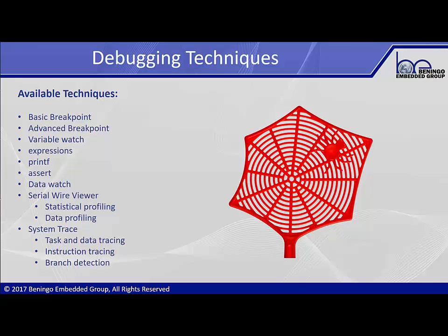So if you have a function that's blinking an LED, you may find that, for 1% of the time, your code is going to be found when it samples a PC counter inside that LED blinking code. Or maybe you're finding that 50% of the time is in some error handler or some type of serial communication handler or something like that. But the cool thing about this is that a serial wire viewer will allow you to get some statistical data that approximates to get you a feel for how the system is actually behaving and where most of its time is being spent.